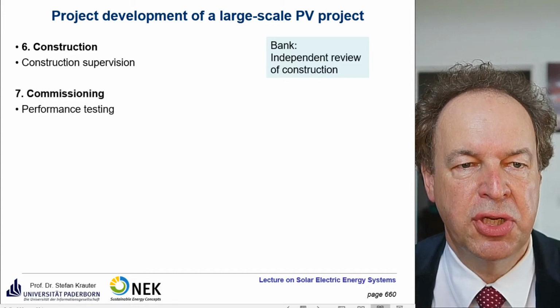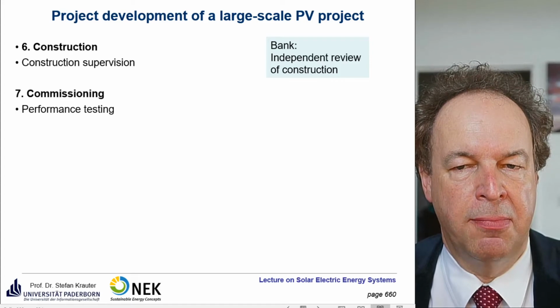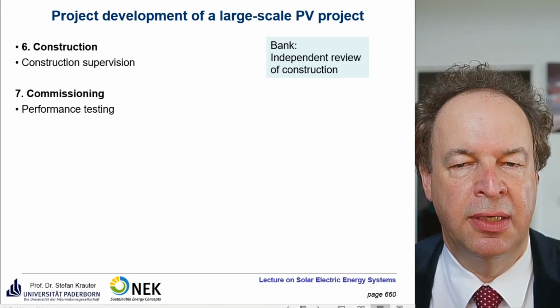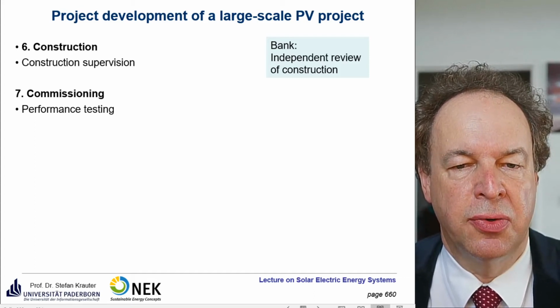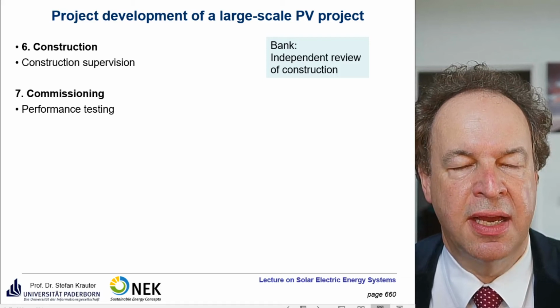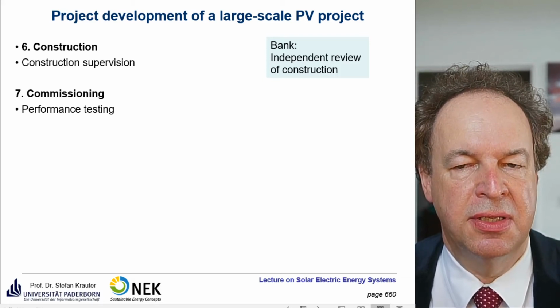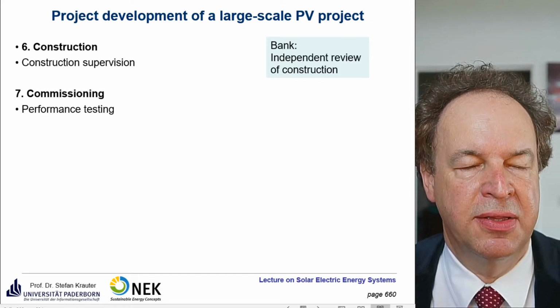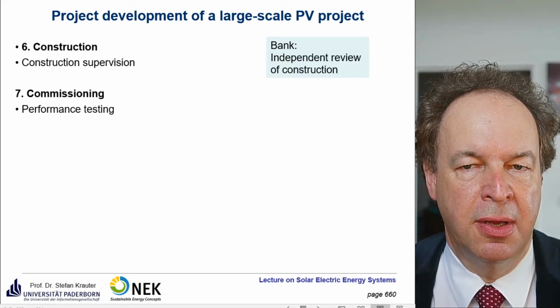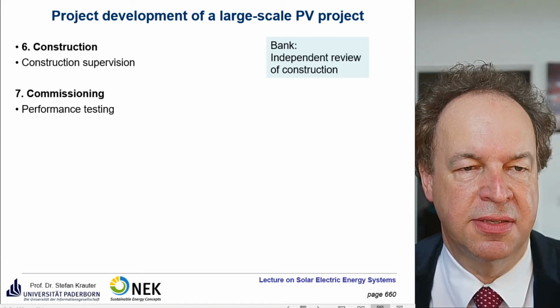And then it's commissioning. So the plant is ready, and you interconnect it to the grid, and before that you do a performance testing. So you measure the irradiance, and you measure the power output, and see what is the performance of the power plant, how much is the efficiency, and so on, as we did in several exercises.